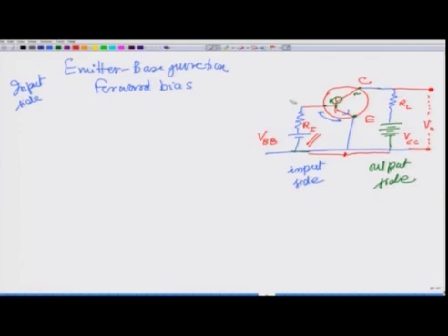Then you have currents. We will talk about how the current will go, but in forward bias, the positive of the battery gives the current. So this is the current going into the base from this battery, and this is known as IB. And then the current will go like this, and here the current will be like this, and this is your emitter current IE. And then you will have a collector current in the opposite direction. Why opposite direction? That we will talk about now.